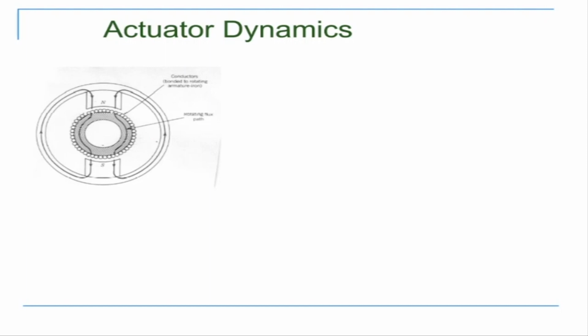We understand the working of a DC motor. There is a rotor inside. So this is my rotor, and this is the stator, which is outside. The stator is a permanent magnet, and there are magnetic lines of force moving, as shown. Now when you pass a voltage through this rotor, it generates a magnetic field. That magnetic field interacts with the magnetic field of the stator, and there is a resultant moment on the axis of the rotor, because of which it rotates.